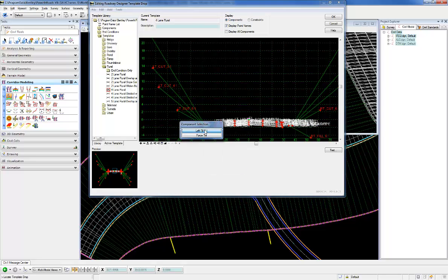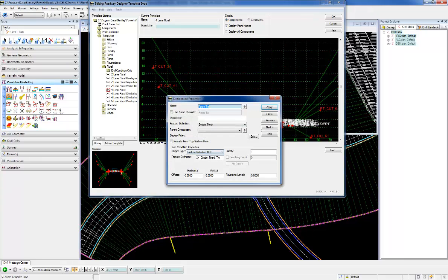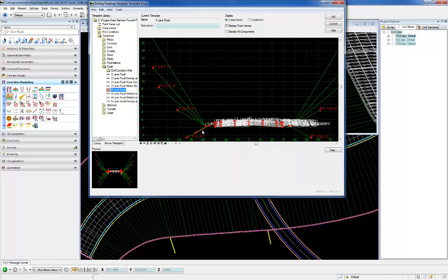Before we go to drop the 6-to-1 slope there, priority 1 is going to be looking for this feature definition. And I have the method set to both, so that both corridors will target the X, Y, and the Z of that line I drew, and so there won't be any overlap and they'll match up exactly at that. And the feature definition they're looking for is the Grade Fixed Tie there. I have that set to priority 1, so if that exists, it's going to find it. If it fails, it's going to go and place the end conditions there.